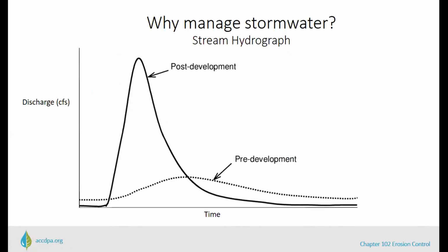So why are there stormwater management requirements for new developments? Developed impervious surfaces substantially change hydrology on a given site. Consider the graph showing a hypothetical stream discharge in a more post-development impervious watershed, the solid line, and a more pre-development pervious watershed, the dotted line. In the pre-development watershed, during a storm, water is hitting fields and forests, is absorbed by vegetation and soils. Eventually, during a rain, there'll be runoff that gently flows towards the stream. The stream gently rises and falls after the storm is ended.